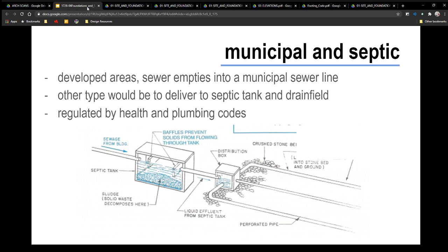The downside, though, is PVC can't withstand heat very well, so it can't be used for hot water. Same thing too with different materials. Copper with soldered fittings has been used a lot for supply piping because it's non-corrosive, and it lasts longer than iron and steel. An issue that we have very commonly in Watauga is that a lot of people use well water here.